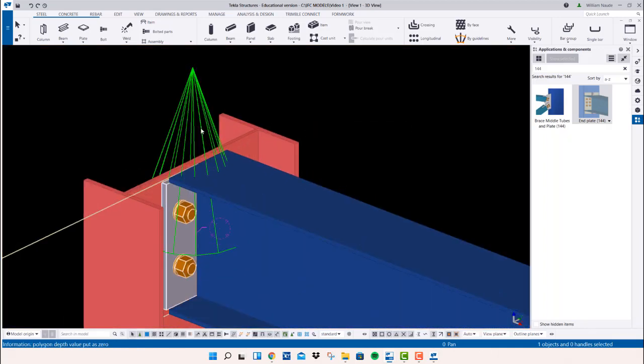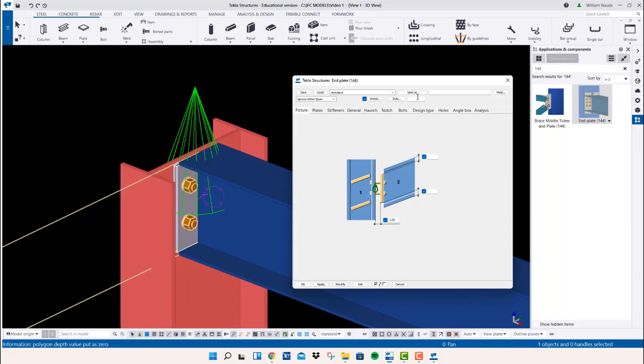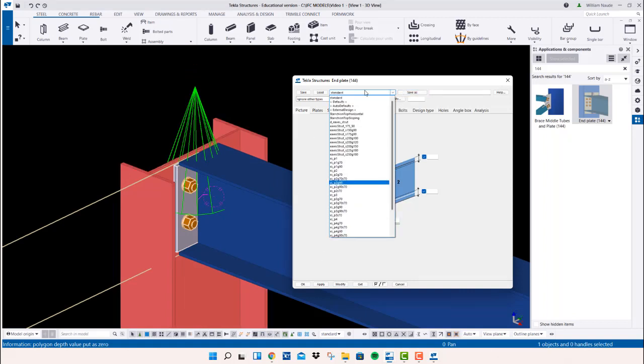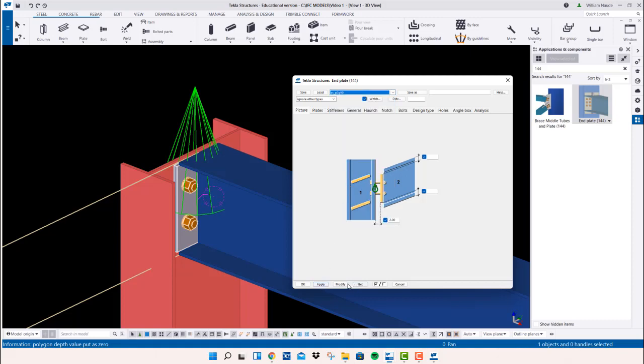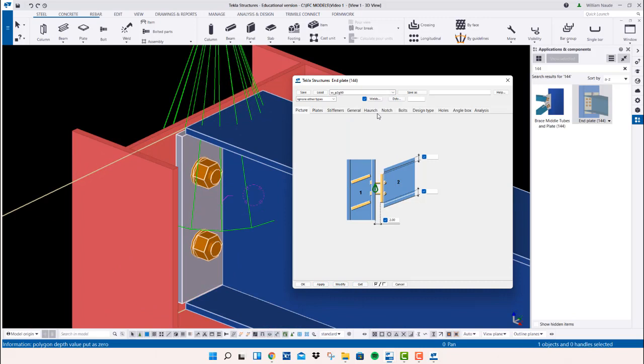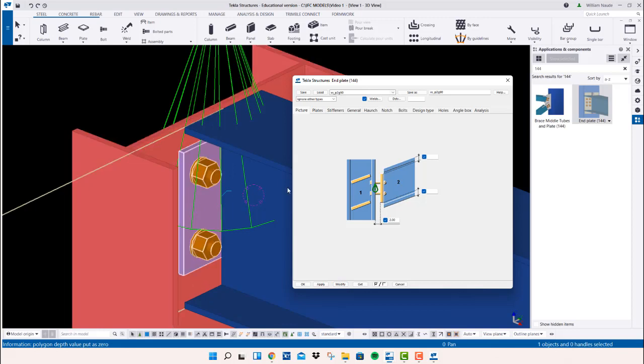We have a column. It's a predefined one that they just put in. Now, Tekla has preloaded settings on some items. So if you want 2 bolts spacing at 70 or bolts at the 90 cross center, you can just load it. You select it, you load it, modify it. It will change, as you can see.